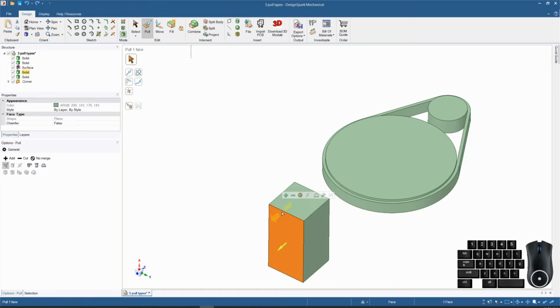And if I just select one edge here, we can go to this middle button here, which is the copy edge. I wanted to show you this really quick. Once you have an edge selected, the 2 different arrows show you that I can copy this edge and pull it down this way, Control Z, or I can copy that edge and pull it across to basically split the face of this solid cube here. So this is a quick, easy way that you can divide up a face on a 3D object. Let's go ahead and throw another one on here, and we'll divide these 2 faces up like this really quick.